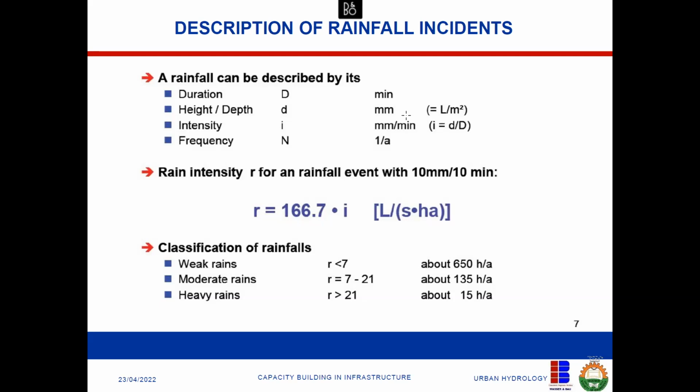So when I now say the 10 years flood event, I'm saying what rain will come at least once in 10 years. In other words, I'm designing for that worst case scenario that can happen 1 in 10 years. So the frequency becomes 1 over 10. It means it can only occur once in 10 years.